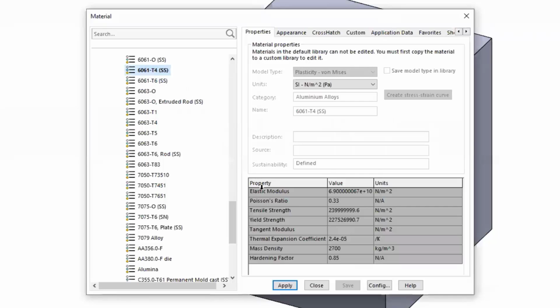When you do this, I would verify the density. The exam is going to tell you what the density is. Let's say if it's in millimeters, it's going to say it's this value in, let's say, millimeters cubed. So you can actually change the unit of measure right here. Select metric, for example. And here it's saying it's 0.0027 kilograms per centimeters cubed. And then just verify that this material is what it's calling out in the test.